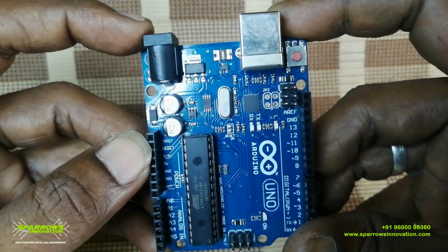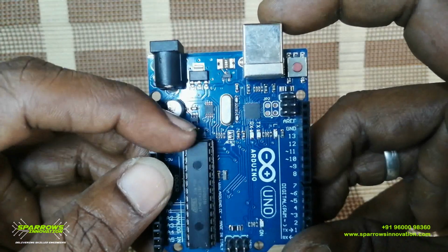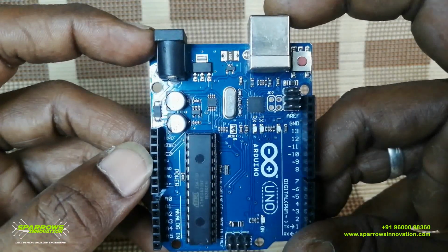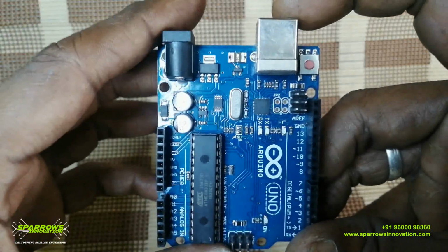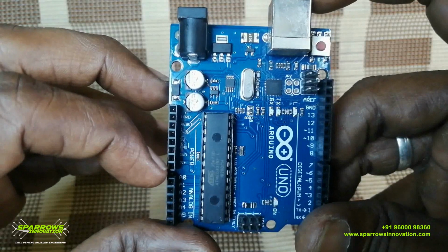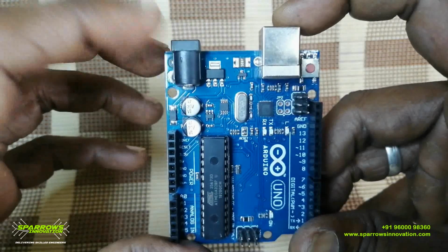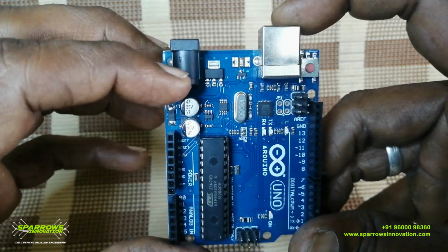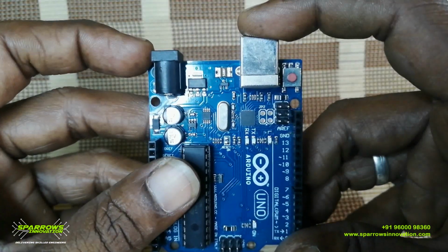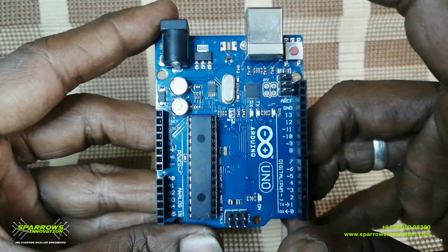When you power this board by using a battery or a USB cable, the voltage regulator will convert that voltage to 5 volt and 3.3 volt. So you can use it for connecting any other hardware to this Arduino board. You also have this Vin pin. You can connect a battery directly to this Vin pin, and the battery voltage should not be more than 12 volt DC. You can also connect the battery by using this DC jack. Here also the voltage range is 9 to 12 volt DC. You can also power it by using this USB port, and this is a reset switch. That's all you need to know about this Arduino hardware.